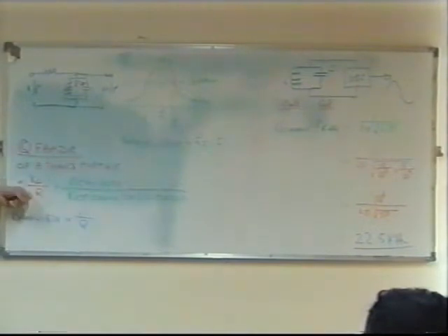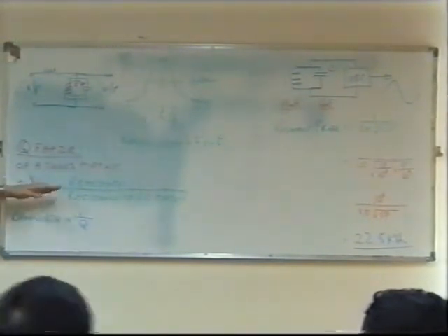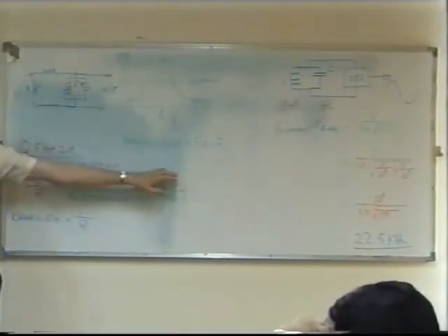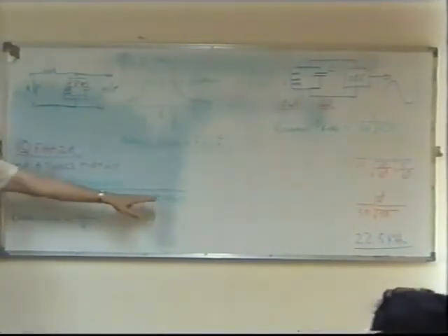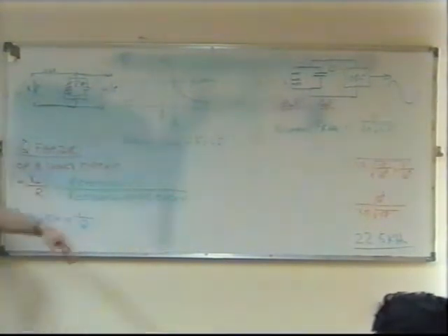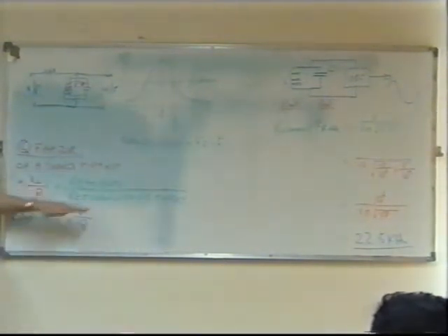All the losses of the circuit are. Normally, for a tuned circuit, this resistance should be very small compared to the reactance. 100 to 1 is a good value of Q factor. In other words, the reactance of the coil, measured in ohms, divided by the resistance, also measured in ohms, may be 100 times bigger. So it gives you a Q of 100.